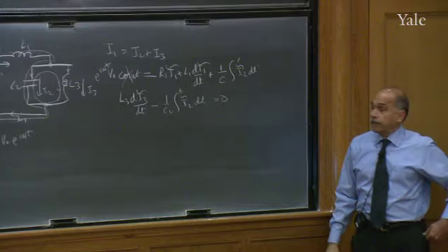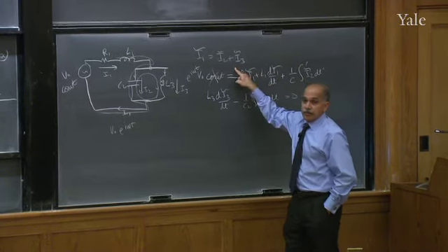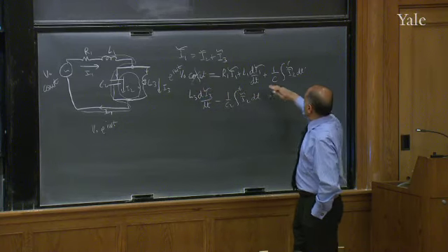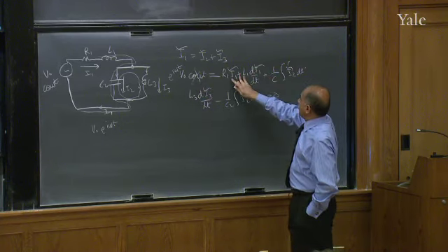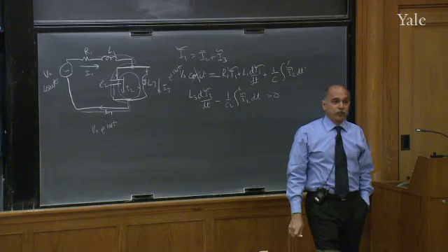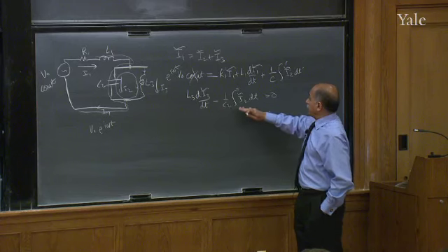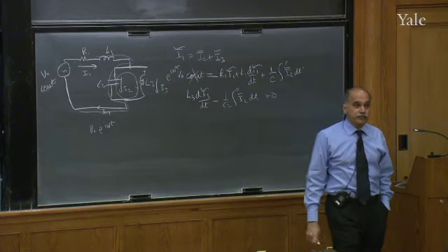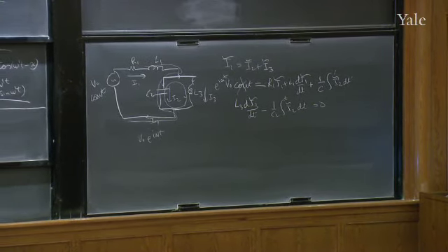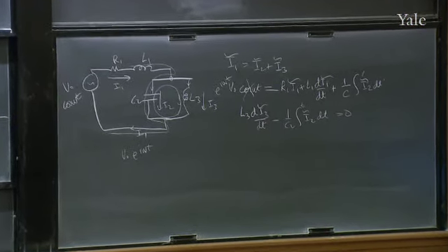Can you see that if I took the real part of the first equation, I get the correct equation for the physical currents? That if I took the real part of the second equation, everywhere I replace I twiddle by the real part, which I call I, and this becomes V naught cos omega t, I get the second voltage equation. And here, again, you drop the twiddles by taking the real part. That's the equation satisfied by the physical currents I2 and I3. So it is still true, even in this complicated problem, that once you solved it, you may take the real part of the voltage and take the real part of the current anywhere. That's the answer to the primordial problem.